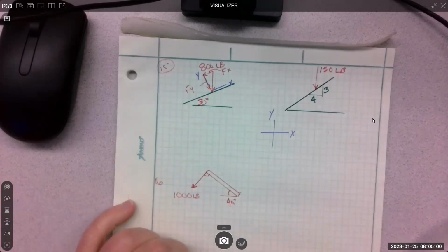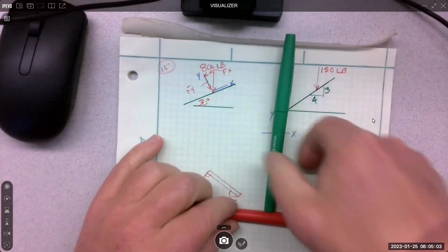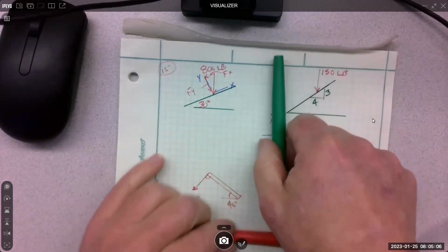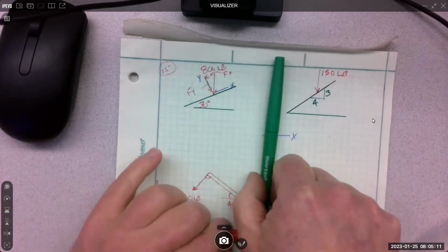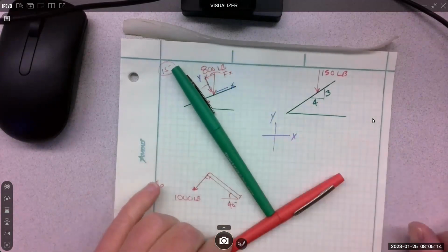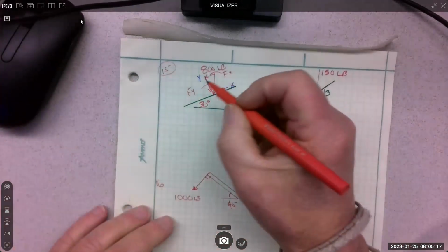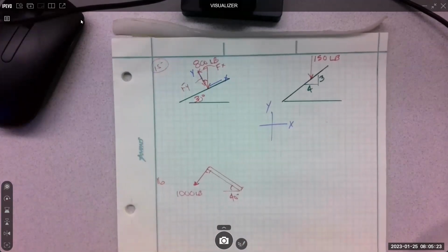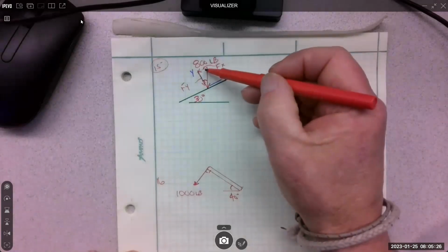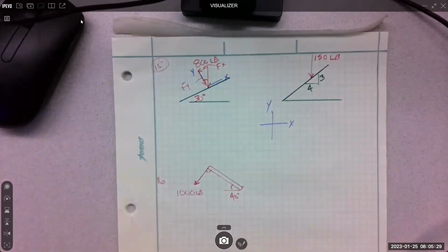The way I think about it is in this position, right? Perpendicular, horizontal, right? As we rotate this, whatever angle the red is on, the green is on to vertical, right? They move through the same angle. So that means if it's 30 here, it's 30 there. If you draw it graphically accurate, then that helps too, because that looks like 30. This does not look like 30. So once you had those two pieces, oh, we're moving the coordinate system. We're still finding rectangular coordinates. They're just not horizontal and vertical. They are perpendicular and parallel to the slope.